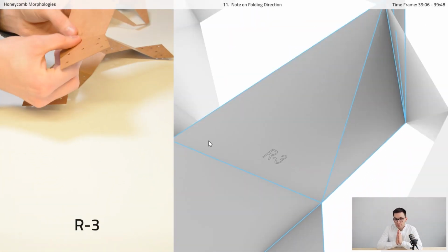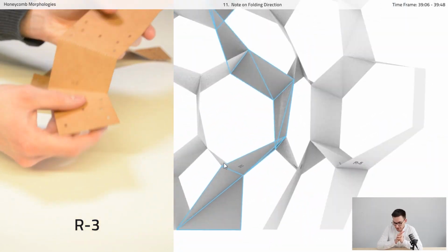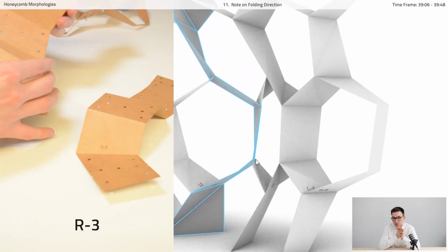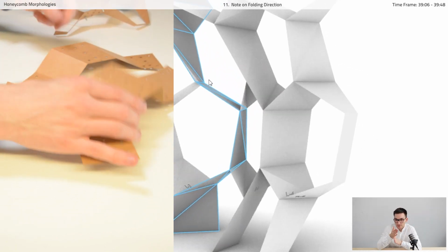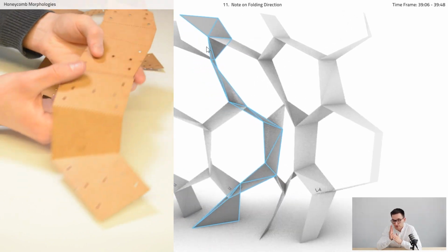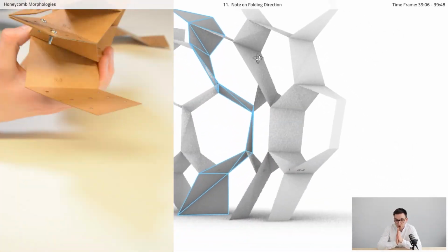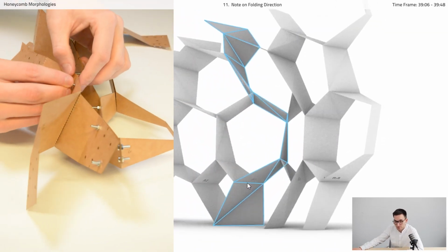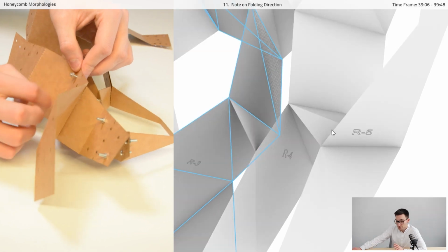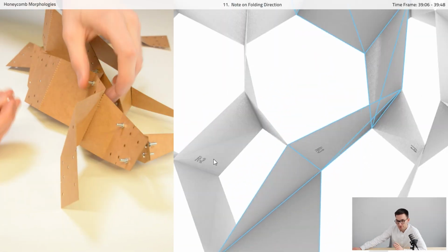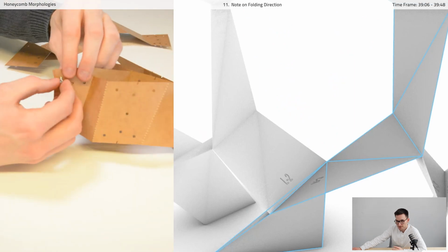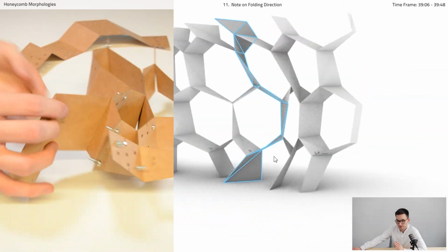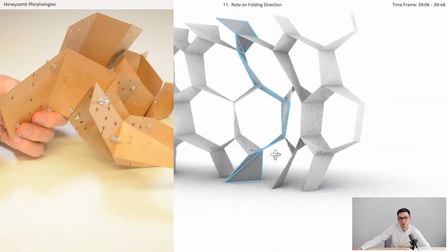It is also very important that you pay attention to the folding direction. If you make a crease in the wrong direction, the respective strip will be broken and will have to be produced again. Therefore, take a close look at the three-dimensional geometry here and pay attention to the text marking for orientation. You can also create a folding template for your geometry if it's not overly complex. It is very important that you work carefully here and fold in the right direction. Feel free to ask us any questions if anything comes up.